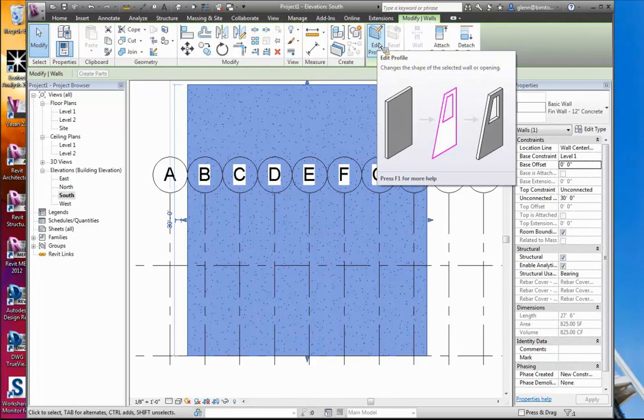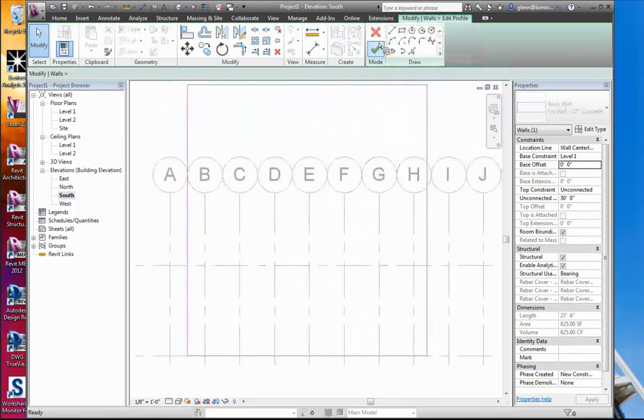And here's the deal. If you're going through and creating a wall, and as opposed to putting door and window openings in it, if you know it just really has a very custom shape, and you just want to carve away the wall material, what you can do is edit the profile. And when you edit the profile, you'll notice we're sort of in pink line mode.